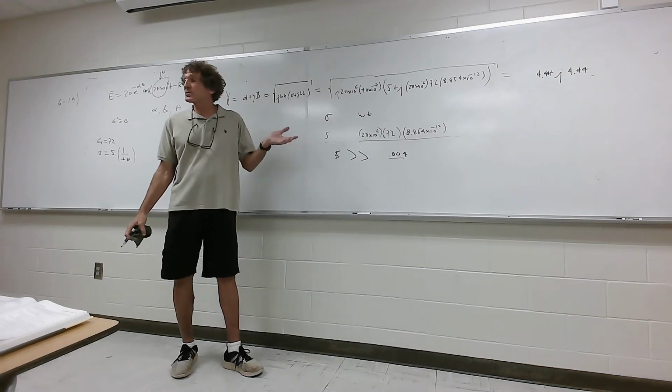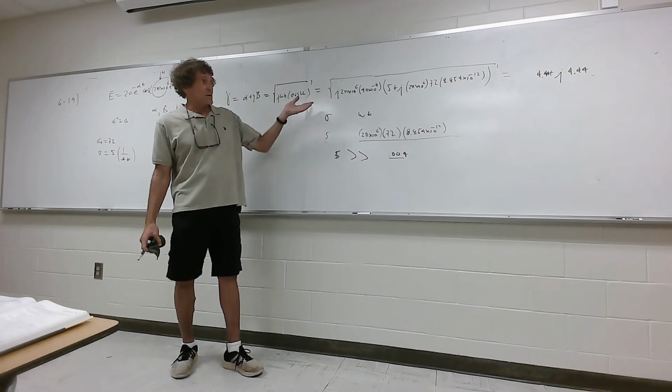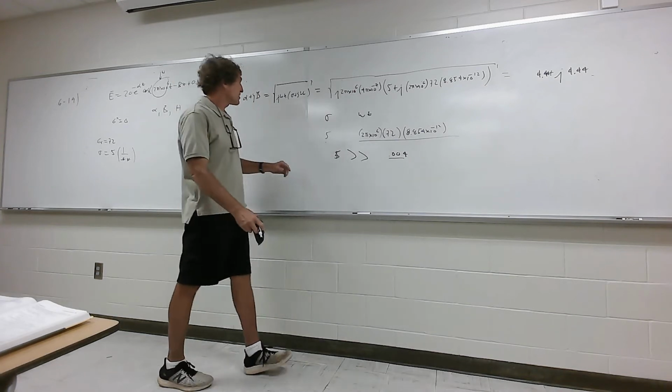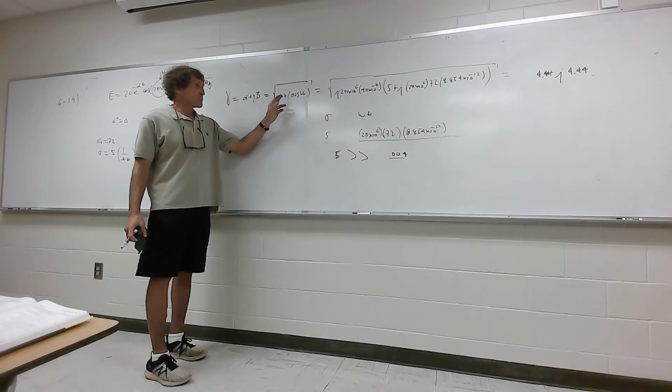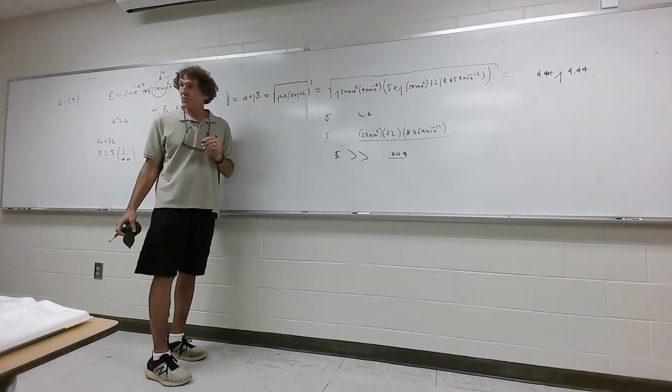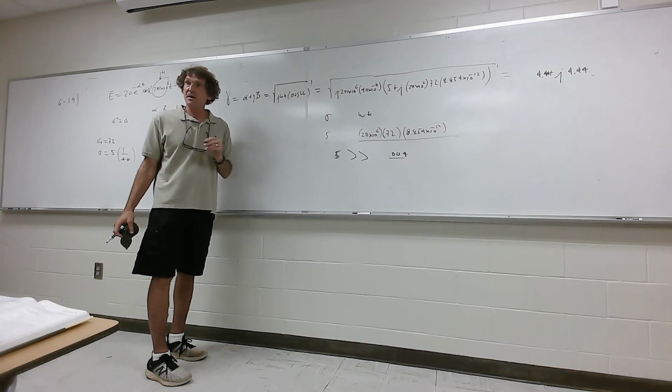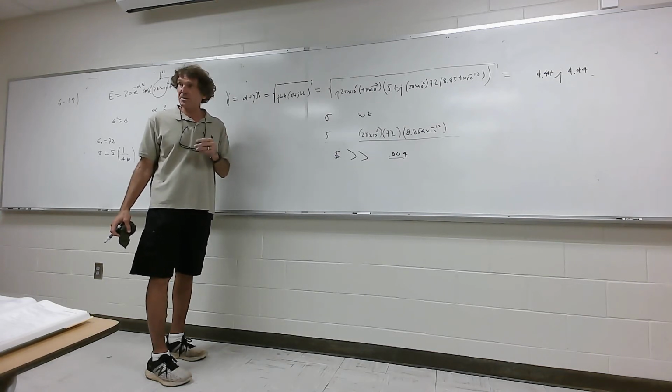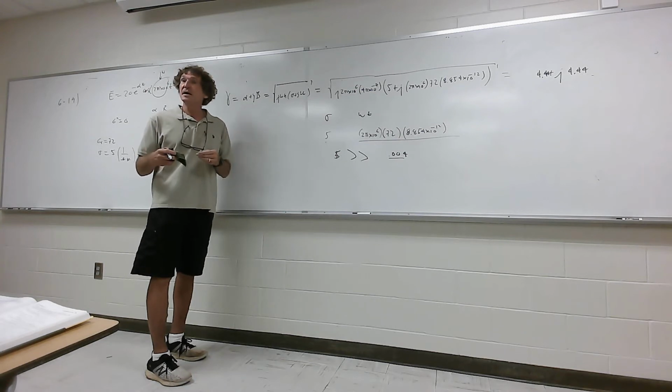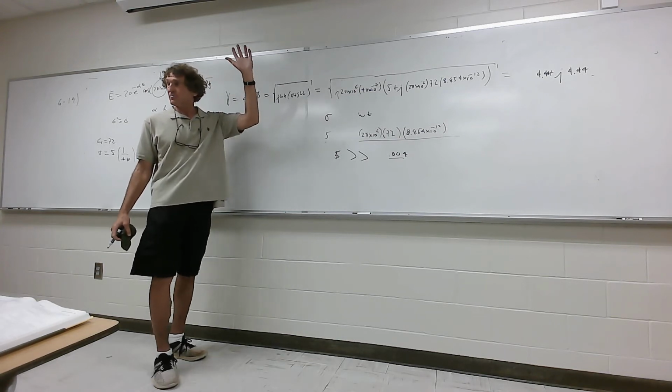If it's a good conductor, you don't have to punch all those numbers out. You can just do what? Square root of j omega mu sigma. You could ignore the epsilon relative times omega. Y'all follow me on epsilon relative epsilon naught times omega? Because it is a good conductor. Do you agree with this, guys? How many students right here? It's a good problem. Now go ahead.